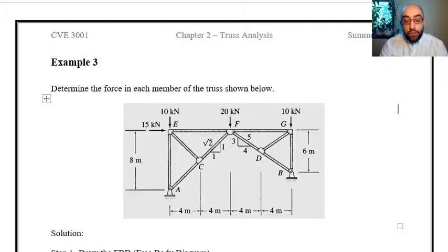And just to remind you about the two important things about truss structures, we have to mention the two properties of the truss members. The first one is that these members don't have any shear force or bending moment. Truss members are always carrying the load through axial behavior, so they are always either in tension or compression.